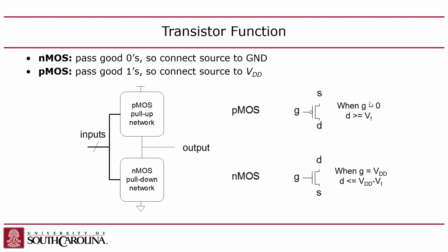If the pull-up and the pull-down network both provide a path, it blows up, right? You can only have one or the other, but ideally, always one of these will be on, unless you have a tri-state gate, which is a specialized gate that you can get a floating output from. But most gates don't have floating outputs. They have a 0 or 1 output all the time, right? You guys with me?